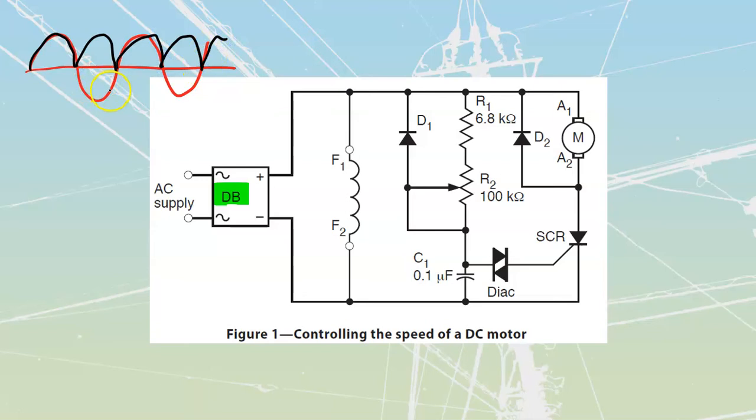It's going to look like that. The black line that we have up top, let's erase the red one down there. So that's what that bridge is going to do. Once again, the important part is that we are going to be hitting that point where we have 0 volts, and therefore we are going to hit that point where we are going to have 0 amps of holding current.